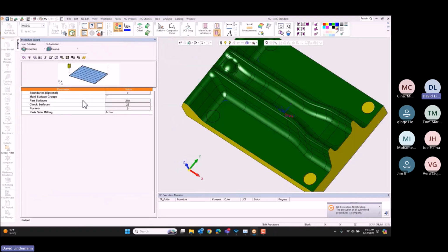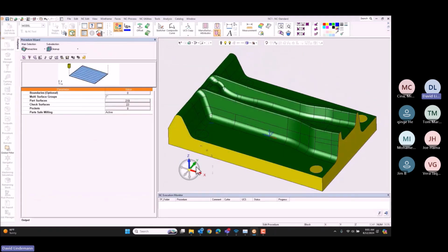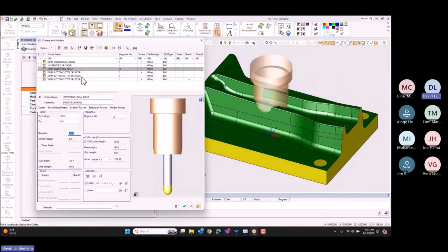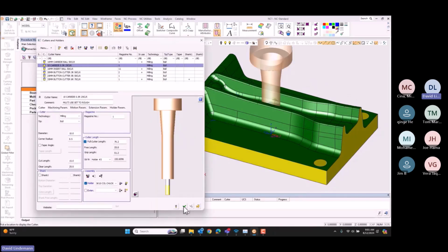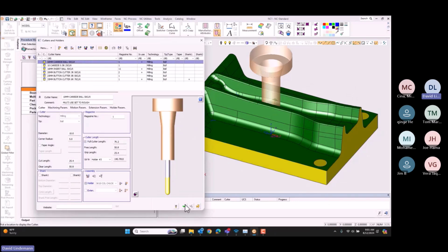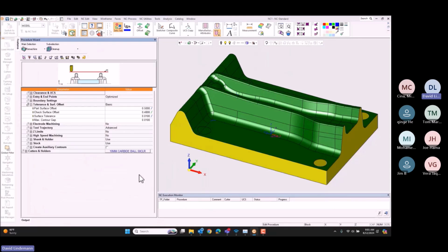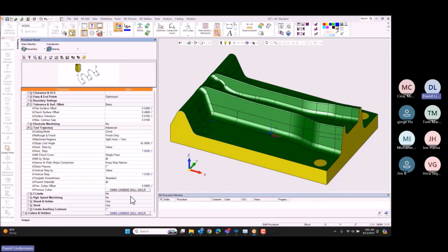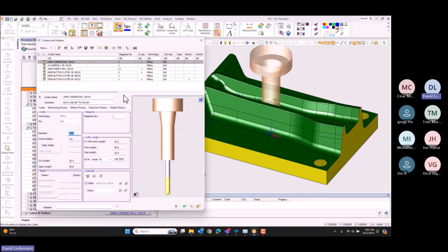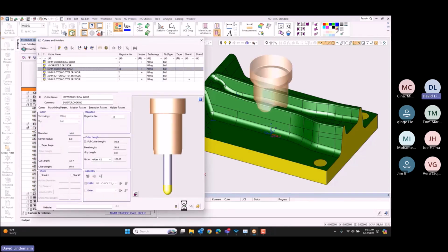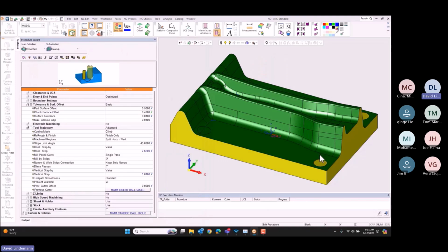So this is a true stock recognition toolpath, just like the others. So it's more than just saying, okay, I know I need to get into the corner that was left behind by this previous cutter. It does use that, like I'm setting up now some cutters to do just that. But it also is going to keep track of stock. So if there are thick areas of stock, I can go back and do like a mini rough routine in there. I'm saying I left everything at 16 millimeter, but now cut it with a 10 millimeter. And then apply the different side steps and vertical steps. So we'll calculate that now.